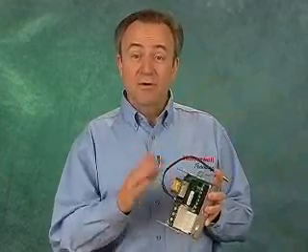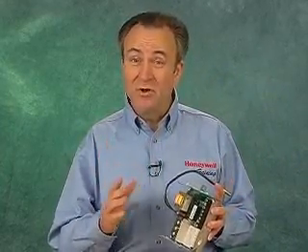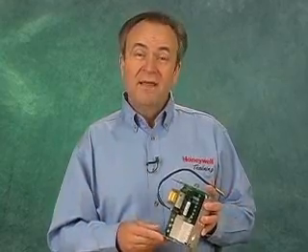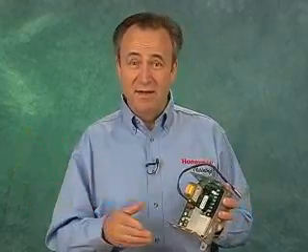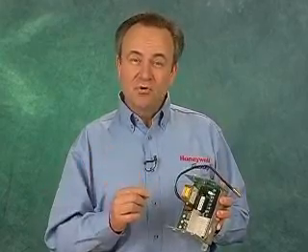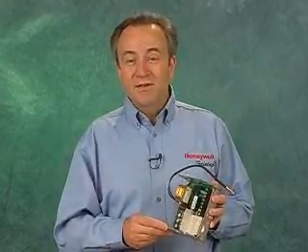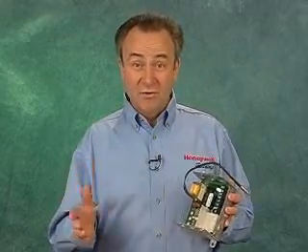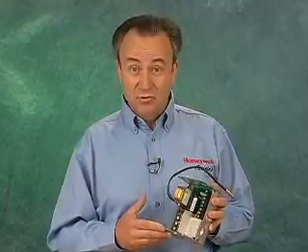This L7224U is the microelectronic version of the triple aquastat relay, designed for use on oil-fired burners. It's been specially designed to replace many other aquastat relays and controllers. The U for universal in the model number is the tip-off that this control is something special for servicing technicians. It replaces both earlier electromechanical devices as well as newer microelectronic aquastat controllers.